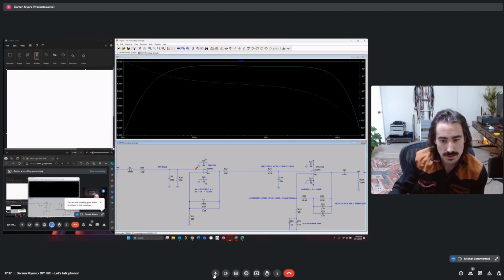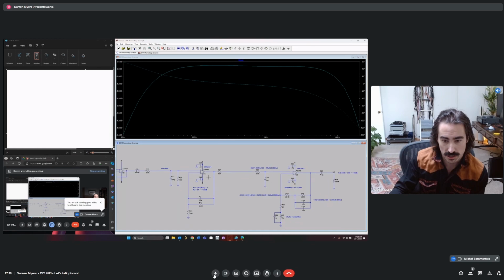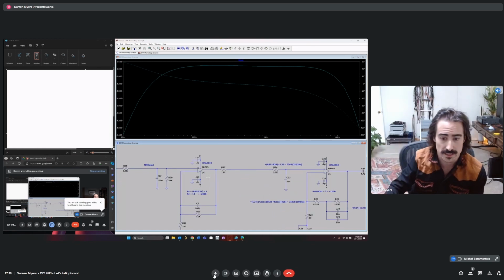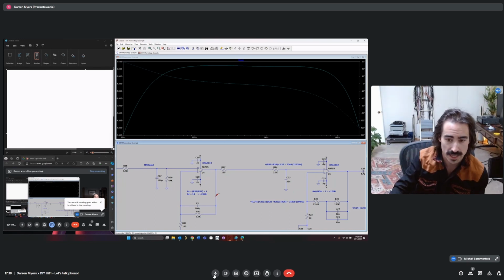So we want an amplifier that has a low current noise spec, as well as a low voltage noise spec. We also need to keep the voltage noise within means as well. And so that's why you could go with OPA2134. It has a very low current noise specification.